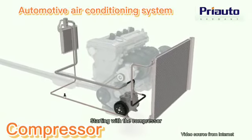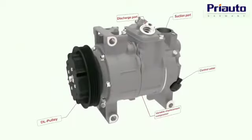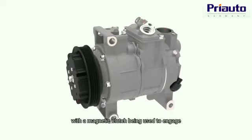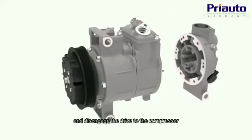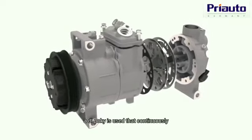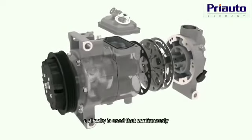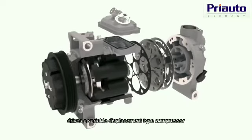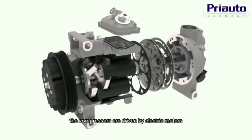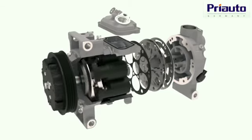Starting with the compressor that creates the flow of refrigerant through the air conditioning system. The compressor is usually driven by the engine using a drive belt, with a magnetic clutch being used to engage and disengage the drive to the compressor. For some systems, a DL pulley is used that continuously drives a variable displacement type compressor, and for electric and hybrid vehicles, the compressors are driven by electric motors.